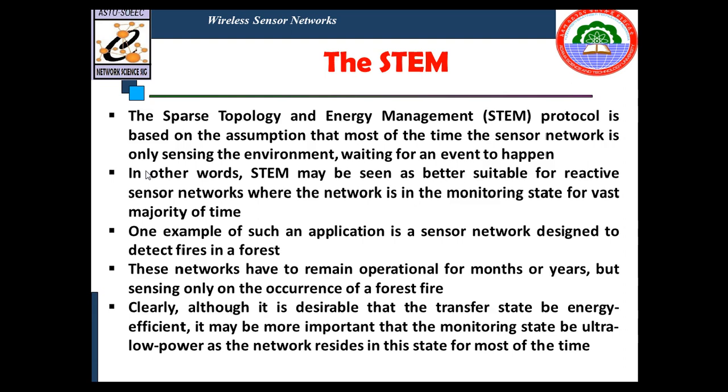The main idea behind the STEM protocol is to turn on only the node sensor and some processing circuitry during the monitoring state. Whenever a possible event is detected, the main processor is woken up to analyze the sensed data in detail and forward it to the data sink. However, the radio of the next hop in the path to the data sink is still turned off, since it did not detect any event. STEM solves this problem by having each node periodically turn on its radio for a short time to listen if someone else wants to communicate with it.